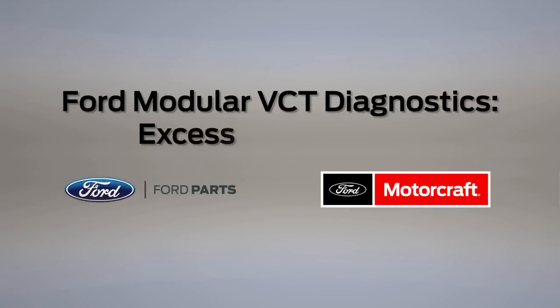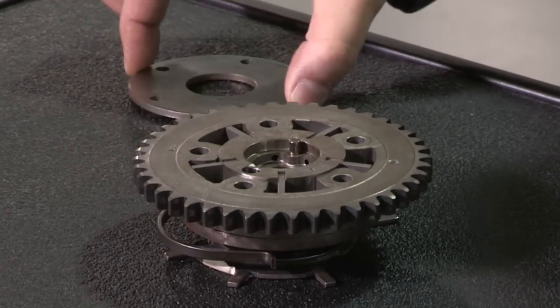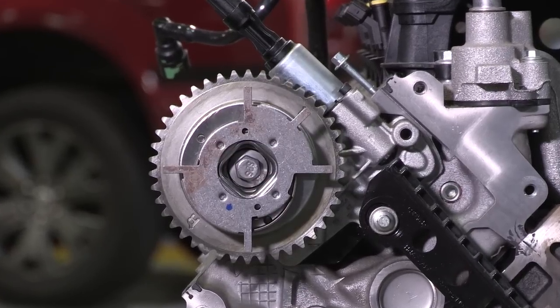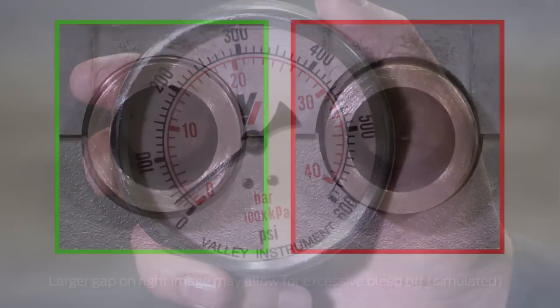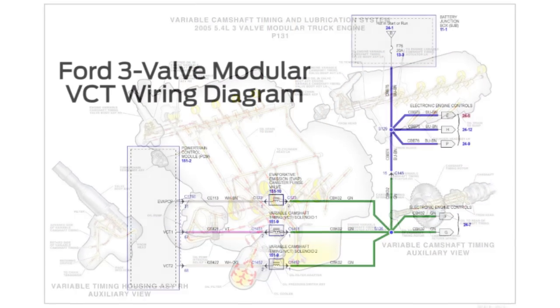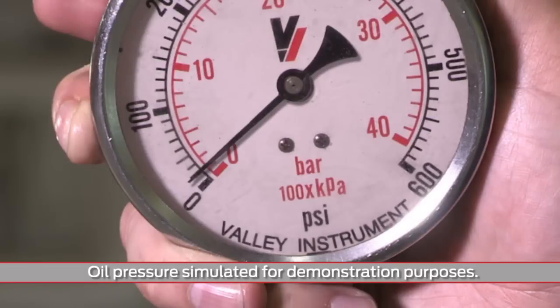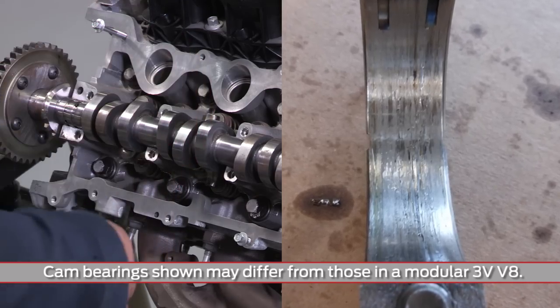When there's excessive oil bleed-off in a modular engine, sufficient oil may not reach all of the components that need it. The variable cam timing or VCT system requires oil pressure and volume to operate properly, so excessive bleed-off can be a problem. If you suspect the VCT system is the issue, make sure there are no concerns with engine oil level, condition, or low oil pressure affecting VCT performance. Then, check for excessive oil bleed-off in the engine.